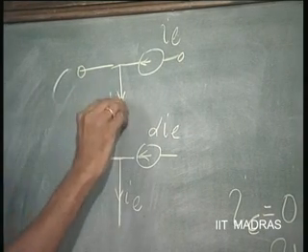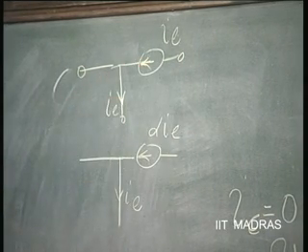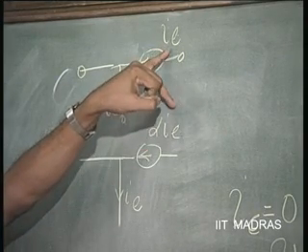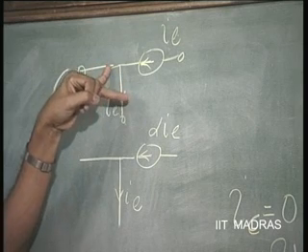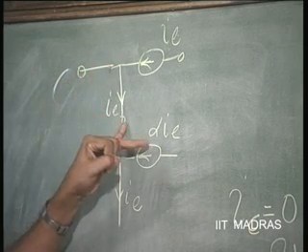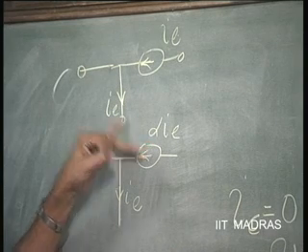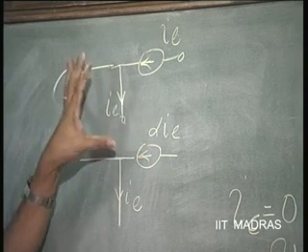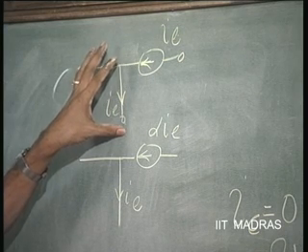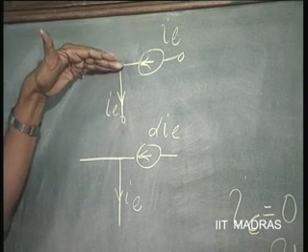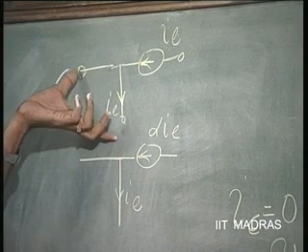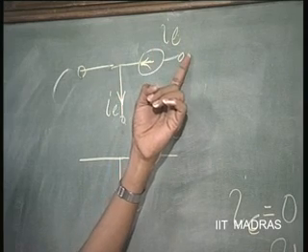And you see here, if you represent this by an equivalent circuit like this, IE is the current source current here. That means the current in this is always 0. Between these 2 points, potential is 0, the current here is 0, and therefore these 2 points were replaced by what is called a nuller, because current through this is 0, voltage across it is 0.